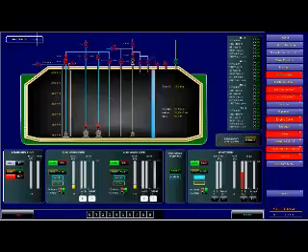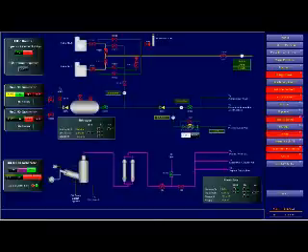We were earlier reliquefying while we were doing the cargo conditioning, but sometimes we use the boil off gas in the engine room. If we go to the engine room, at the moment our boil off gas valve is closed. Why have we closed it? Because we have done very recently the ESDS test. In the ESDS test or operations, this boil off gas valve will automatically close.